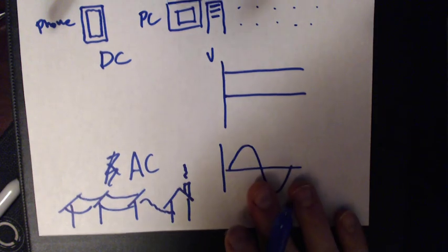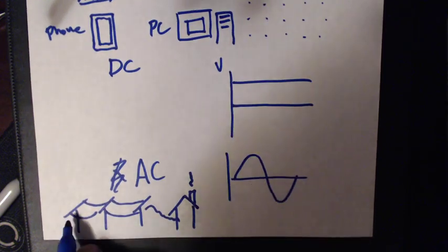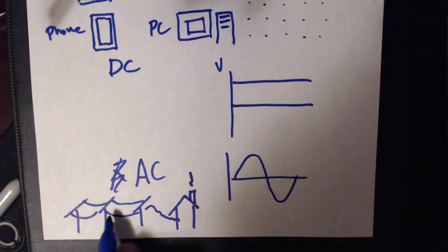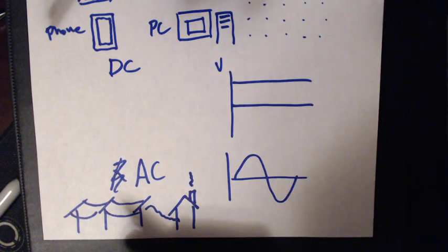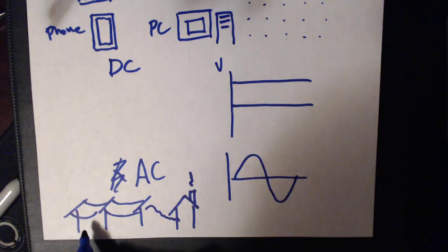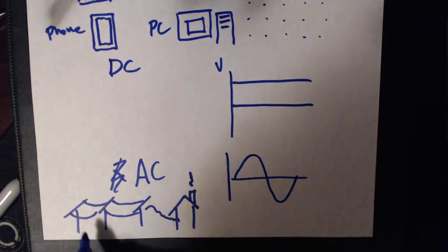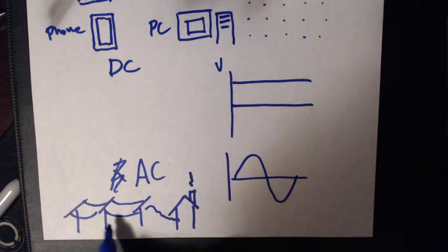And the reason for this is because these long lines, a wire is not a perfect 0 ohms. I've been treating it as such on the board, and for small circuits, the resistance is negligible. However, the resistance of these enormous mile-long lines starts to add up.